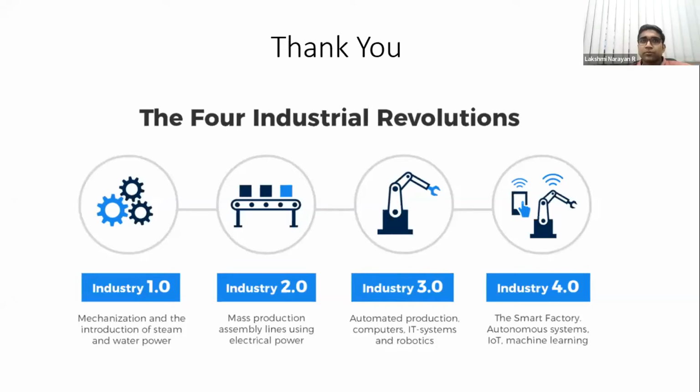Okay, yeah, that's a good question. Generally, fatigue is a surface phenomenon. Superficial as in it occurs on the surface. Okay, I shouldn't call it a superficial phenomenon. Rather, you could say that superficial features on the surface cause fatigue. Any sort of kink or any sort of defect on the surface causes fatigue.